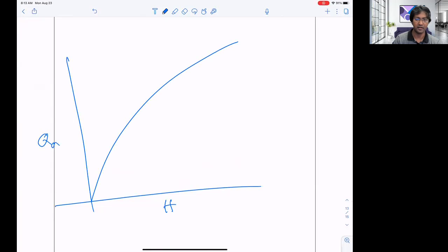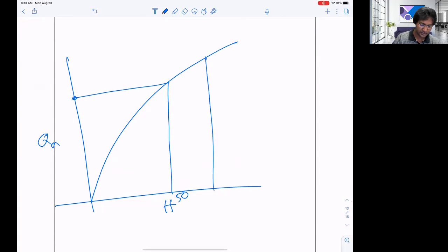Then we'll have a curve like this, and then you can calculate. For example, if we need the value of QA at 50, you can read it from the graph directly. You don't need to calculate using a calculator. You can prepare this graph and paste it on the orifice meter or on the tank. Then someone will measure the actual head and read from this graph. So that is another way.